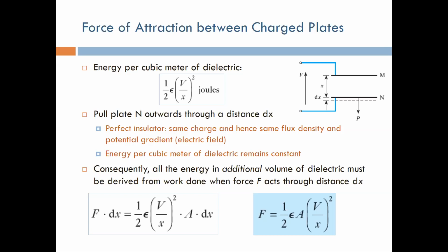Basically, this is the basis of the rating of the voltage for the capacitors. The rating is based on what the capacitor can actually withstand. If the dielectric cannot withstand this kind of force, this force will overcome the dielectric, and you will have a short circuit inside. And this short circuit is responsible for the kind of fires or explosions that you actually saw in the videos that we showed in that first lecture.